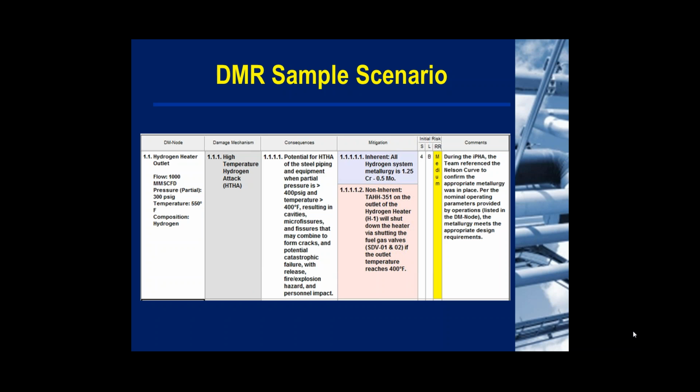As far as risk ranking is concerned, the name of the game here is synchronization. We want to keep it exactly the same as the HAZOP. Keep the IPHA, keep one risk ranking matrix for the entire IPHA. And this provides two major advantages. Number one, you have consistency, like I said, throughout the IPHA.